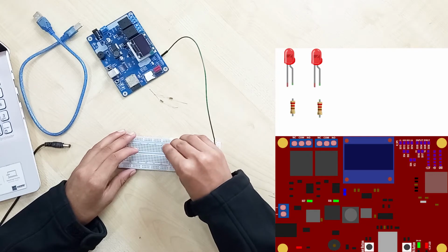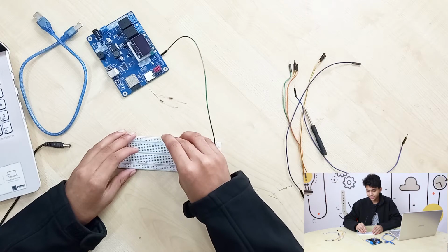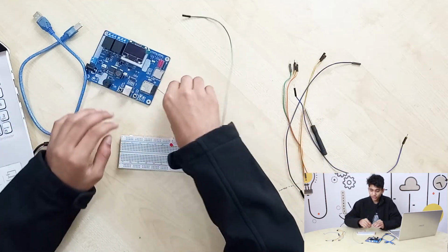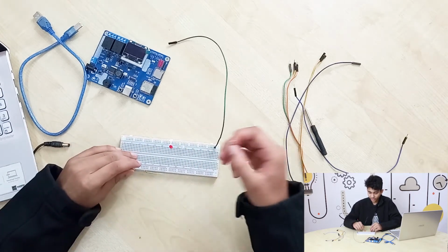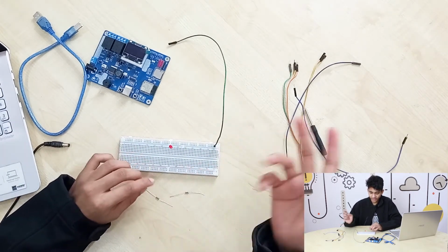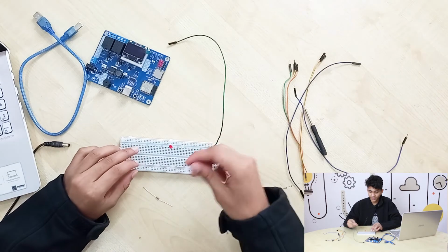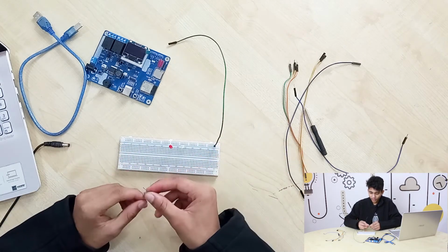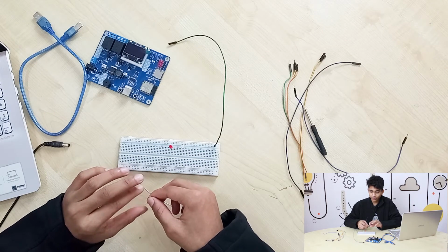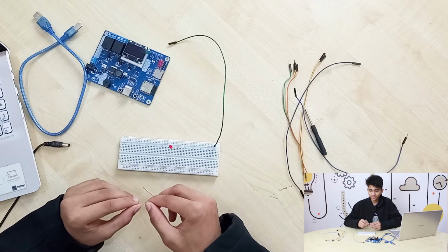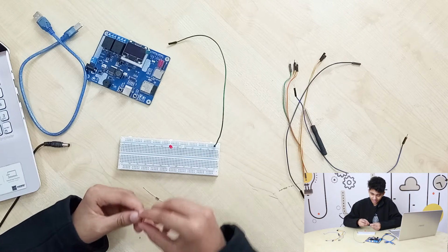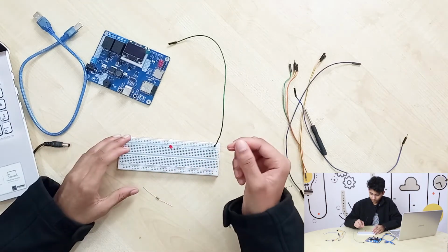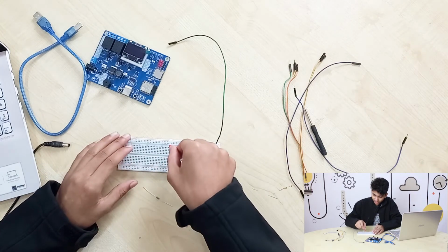So we've connected our LEDs. Let's connect it with the School of IoT board. But at first we're going to use these 220 ohm resistors. As I have mentioned earlier, the resistor is used to limit the current because it's going to burn our LEDs soon. Resistors don't have a polarity, which is a good thing, so we don't have to worry about things like that. So let's connect this resistor with the anode pin here.